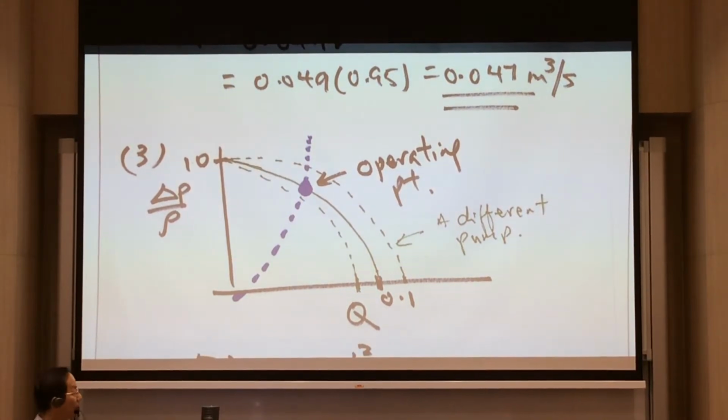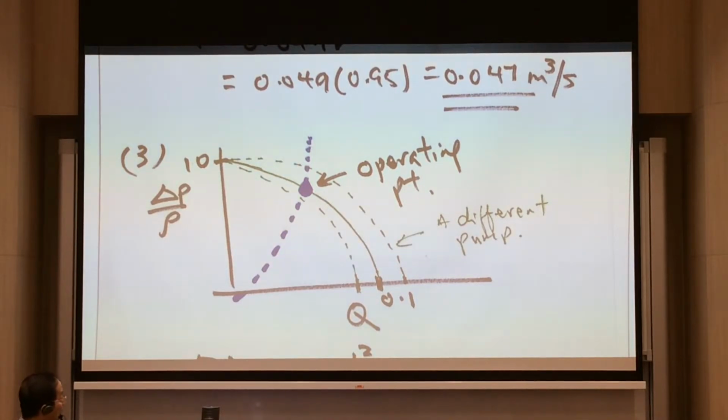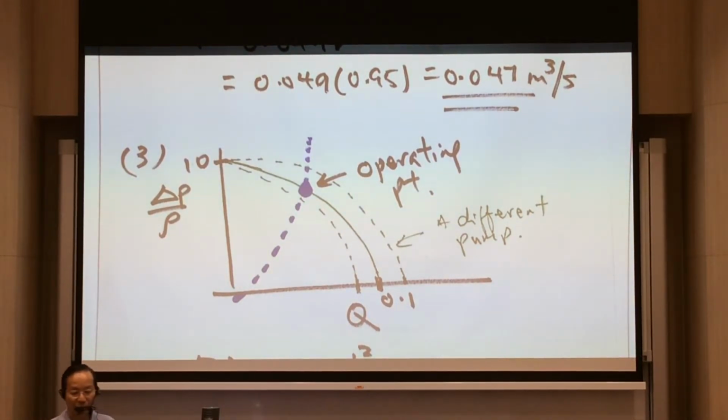So in other words, if you have a pump in a pipe, and the pump is pumping flow at a certain flow rate, and you have a pipe system that follows this characteristic curve, when you size that pump, you want to make sure that you utilize it at the optimum point. If undersized, you will not be able to produce the flow from point A to point B. If it's oversized, then of course you're paying for something extra to what is required. So you want to operate at the ideal point, where you maximize the potential of the pump. This is called the operating point, where the pump characteristic curve and the system curve intersect. So that is the ideal point. Alright, hope that's clear.